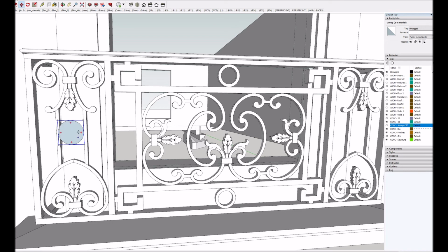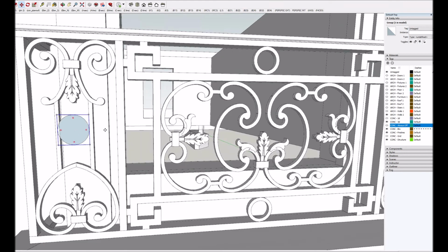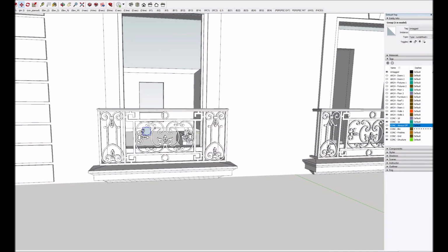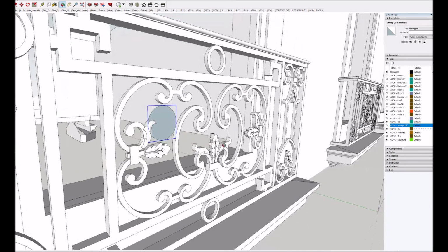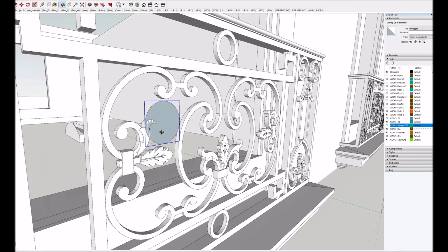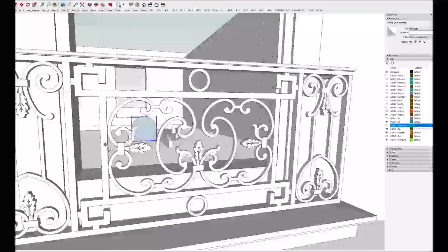So you see my 4-inch circle here would be blocked. I actually added these little curlicue things here because I had a gap here that was slightly too big. If you picture the balcony without that, if you picture it without this little curl, the space here would have allowed the passage of a 4-inch ball. So I added that piece to block the passage of that ball. So that's just one more little code thing that you have to consider as you're working on the design.